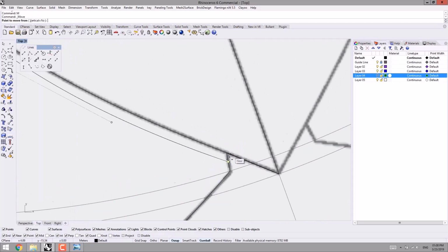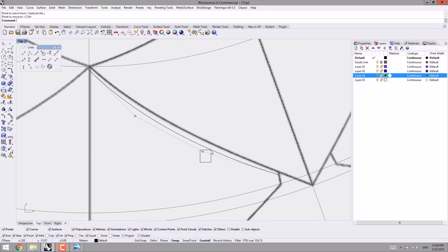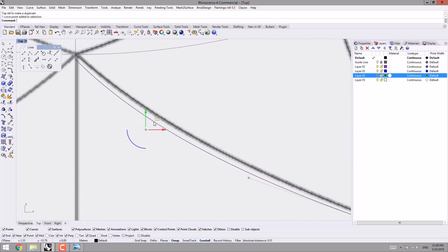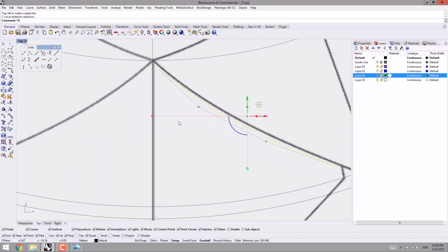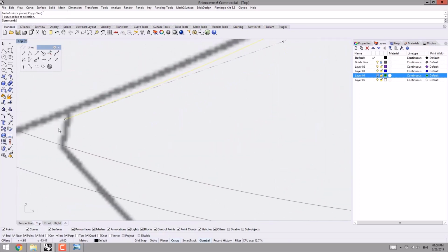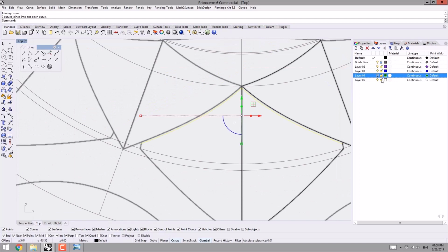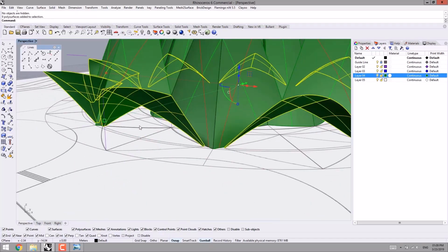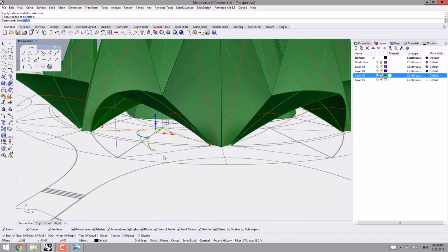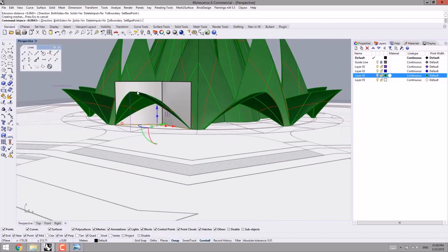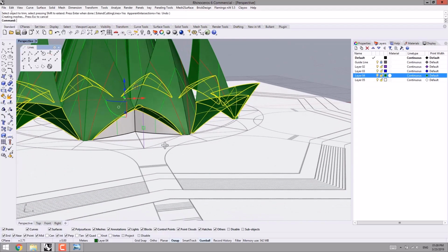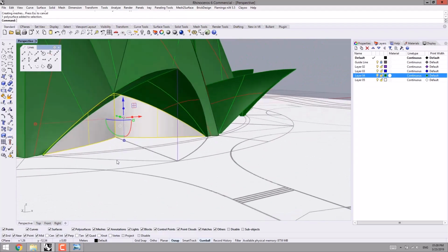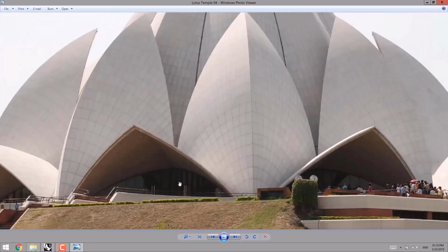However, in the future sessions, we will teach you how to extract some curves from the created surfaces. But till now, since we haven't covered those topics, I consider a small gap and then mirror by this way. Following that, I select them and then join them, and then I select this line or curve, extrude by this way. I select the surface, trim, then I trim the surface or the extrusion actually like this way.